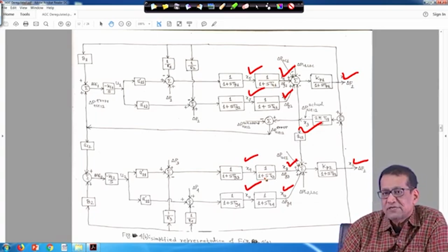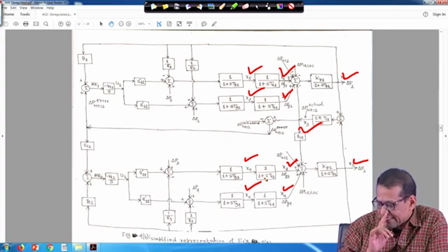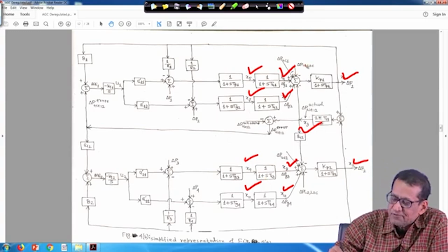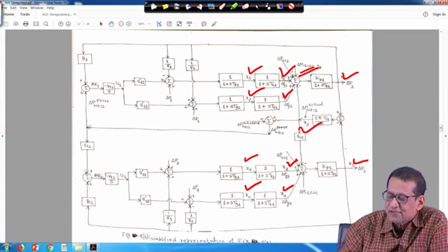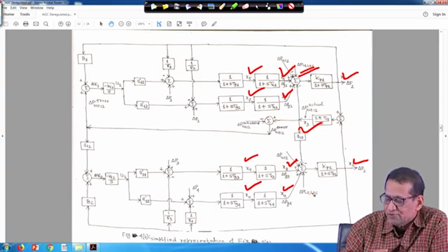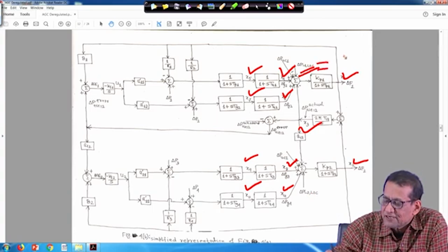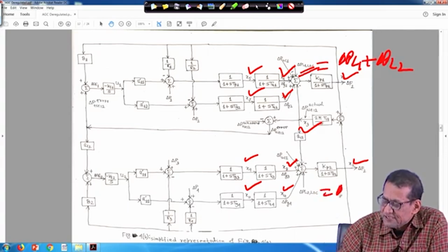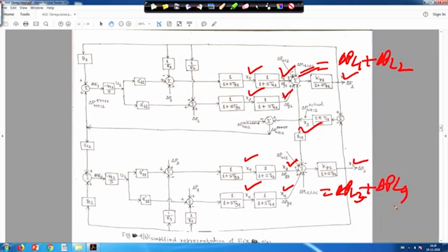So, A matrix will be 11 into 11, but another thing is that here one is the contacted load demand, reflected as a local load demand, that delta PL1 plus PL2 will be there. Here also delta PL2 local. Actually delta PL1 local, I told you, is equal to delta PL1 plus delta PL2, and this one, delta PL2 local, is equal to delta PL3 plus delta PL4, right.